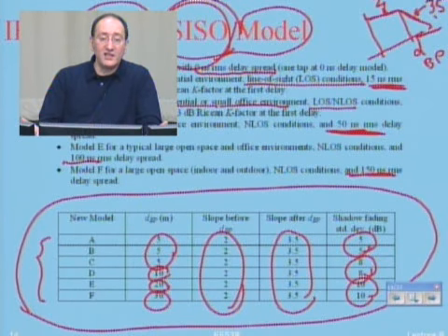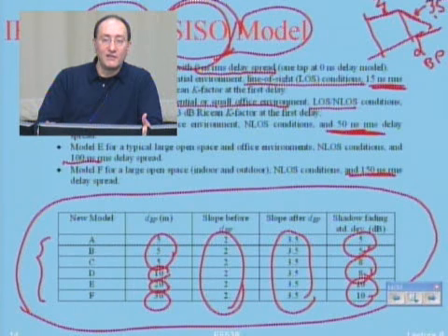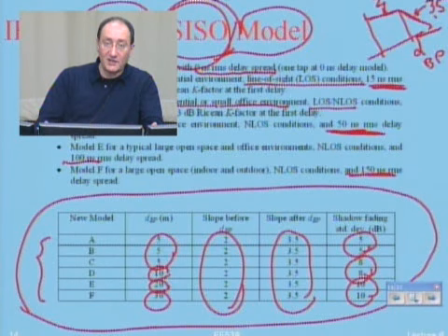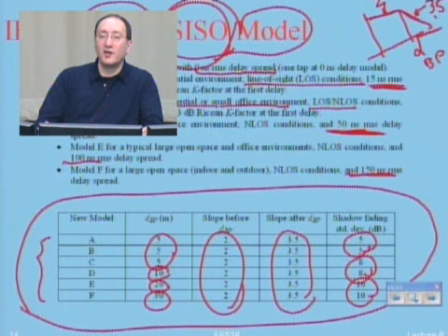But these are all engineering things. And the essence of this engineering modeling is defining three things. One is the path loss for coverage, which we called narrowband modeling. The other one is Q sub tau, the delay power spectrum, which tells you what your data rate limitations are. And then what is the third? The Doppler spectrum.